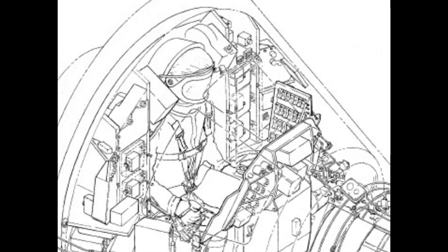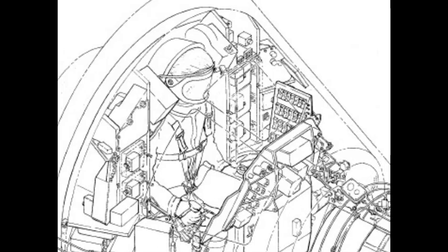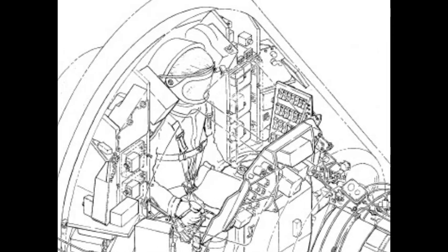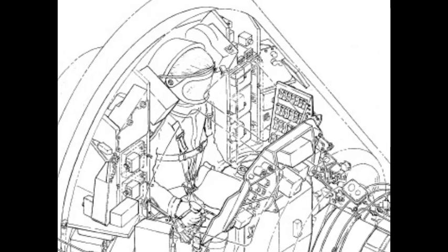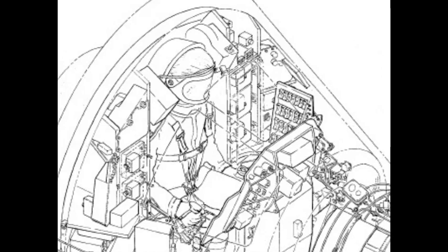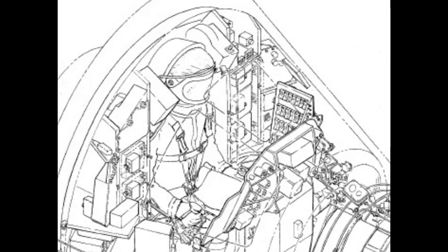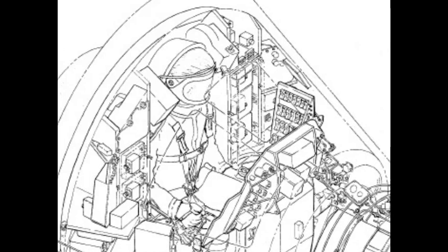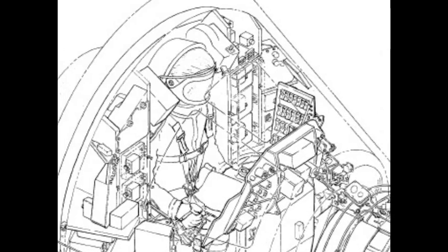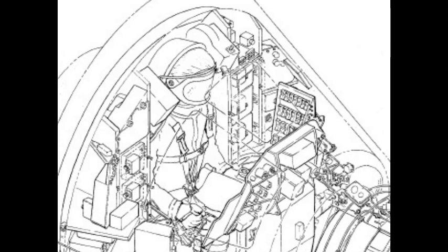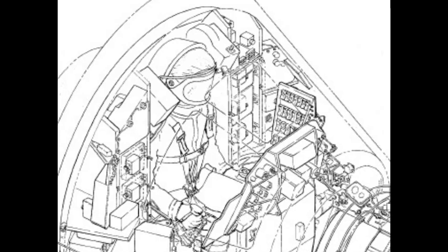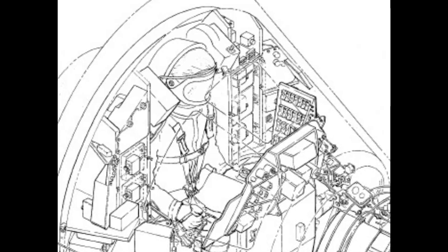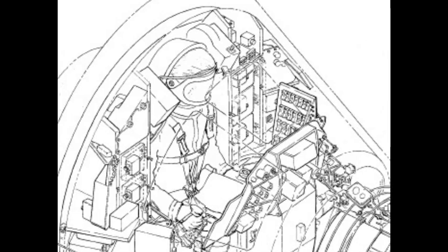An aluminum biconical horn is internally located at the base of the antenna fairing. An electric insulator and lock foam, located above the biconical horn, aid in antenna fairing insulation. A pitch horizon scanner is located at the top of the antenna fairing. A roll horizon scanner is located in the side of the fairing, in line with the pitch horizon scanner.